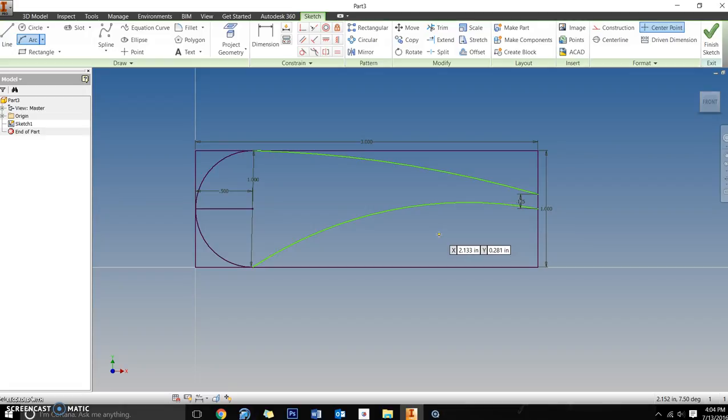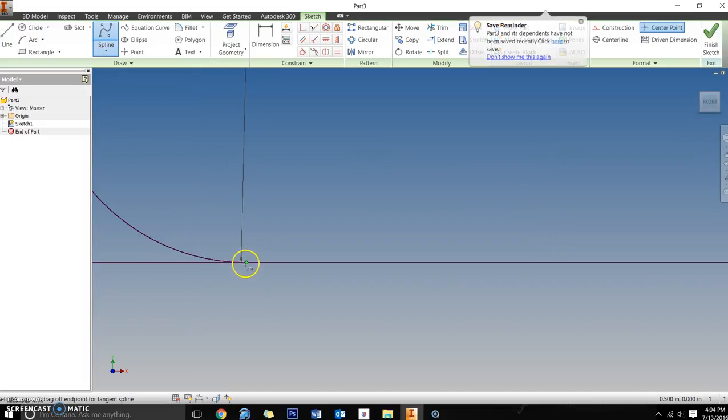Alright, to show you another tool, you can kind of see the general shape that I'm making here. To use a different tool, just to show you guys, it's called a spline tool. It's a freeform drawing tool. I'm just going to Control Z that bottom line. Let's say I wanted to make a freeform line. So that's my spline tool. And with the spline tool, I'm just going to zoom in a little bit. I'm going to click on that snap point.